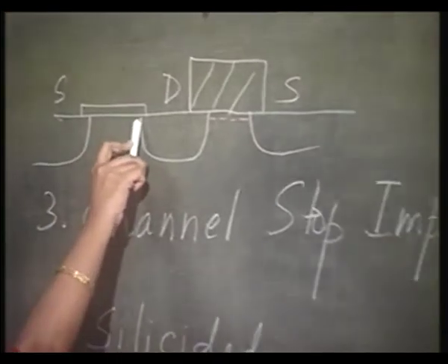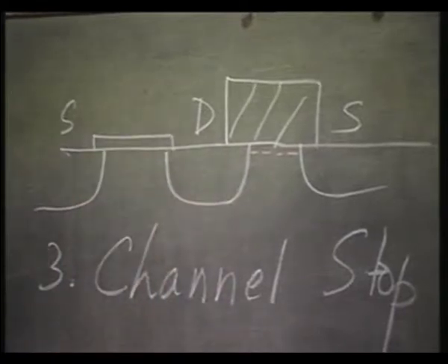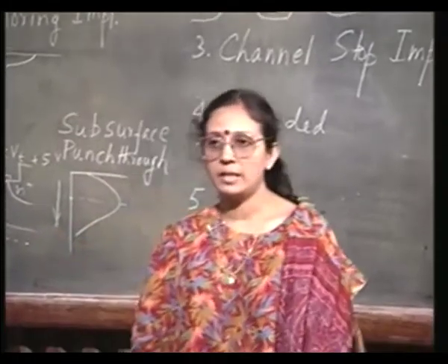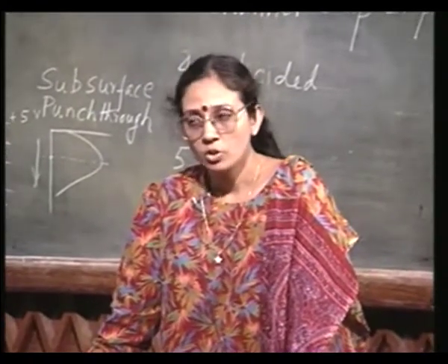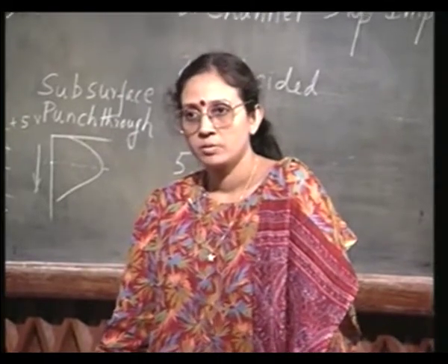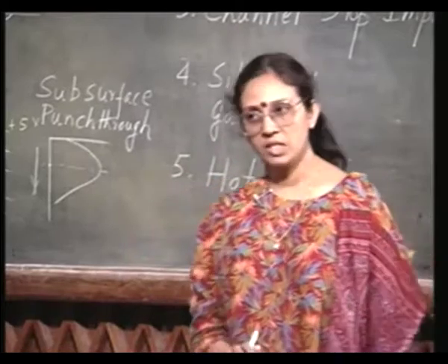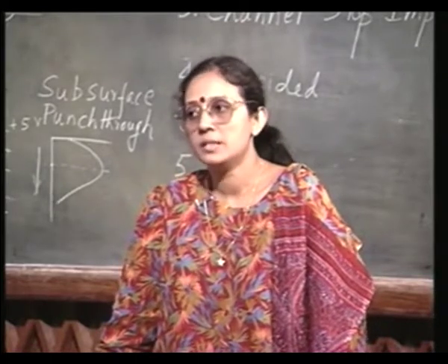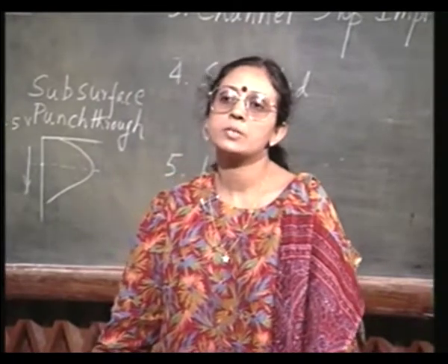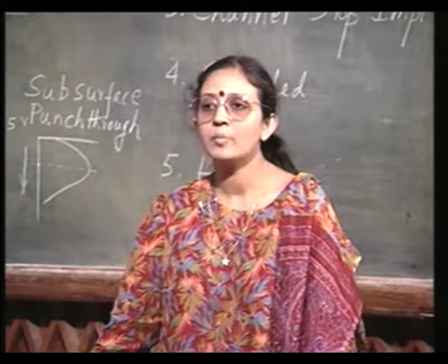Electrons are moving from source to drain. As they reach the drain end, they might have sufficient energy to surmount the silicon dioxide barrier and get injected into the gate. If it gets injected into the gate, then it is going to create oxide trapped charges there. So, the threshold voltage is going to be shifted. Okay. So, they can either create oxide trap charges or they can create interface states, in which case in general the threshold voltage will change, and this is called the hot electron injection. So, hot electron injection is finally going to set a limit on how long your device is going to perform adequately. Okay. It is characterized by MTF, mean time to failure.